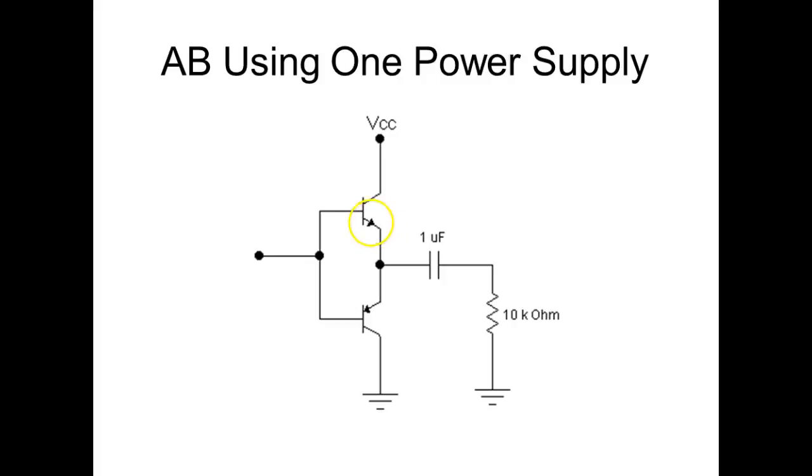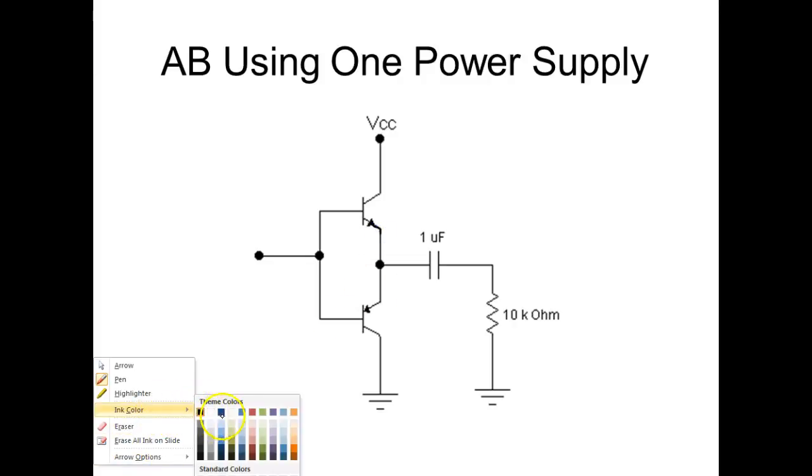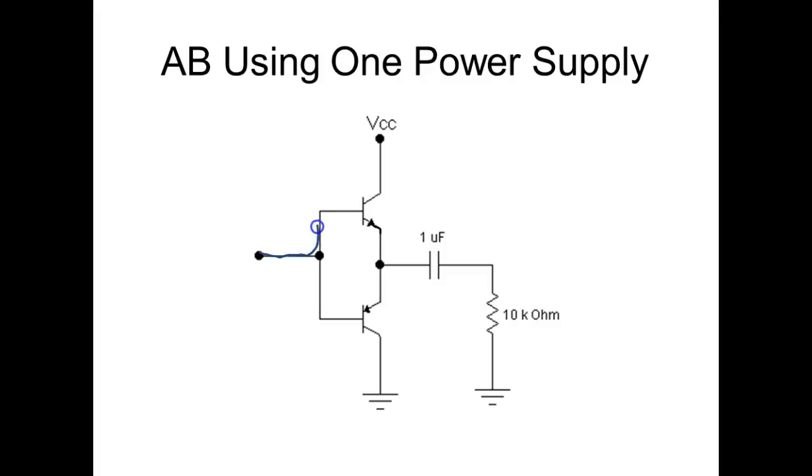Yeah, here's the emitter. So let's just look at one of them. So here comes my input to the top one. It inputs on the what? Base. We're outputting on the emitter. So what type of amplifier are these? Common collectors. Right, you understand. My input starts coming positive. Well, this guy right here is a PNP.